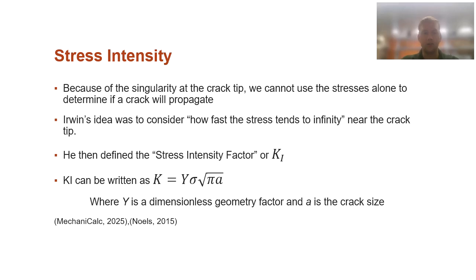And he coins his term as the stress intensity factor, or K1. That 1 again is the mode 1 of our cracking, the opening. And similarly, K1 can be written as this nice equation where we take into account stress and crack size as our variables for our stress intensity factor.